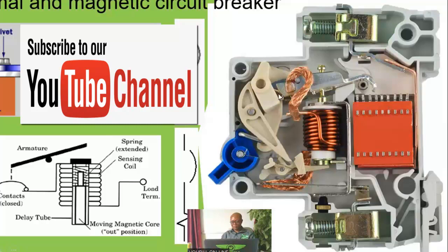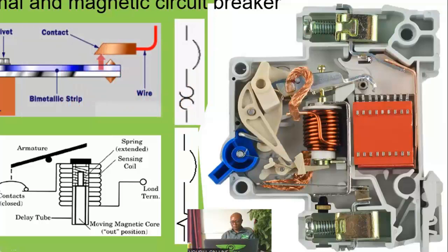We'll see that later. And then this is the trip mechanism, okay. So that is why it is called an electromechanical tripping device, okay. An electromechanical device that is meant for switching your circuit on load, okay. So now if you look at this trip mechanism, when you switch on the breaker, that will help to close this contact, okay. So once this contact is closed, you see that this latch will move to this other slot for holding this latch, okay.